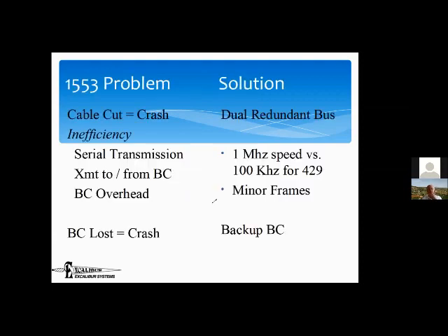Okay, so now let's talk about the pluses and minuses. We'll start with the minuses. And the first minus is that by virtue of the fact that we've reduced 16 wires down to 1, you've also got a single point of error for every single device on the bus, right? And if the devices on the bus are things like radar, engine, landing gear, you really don't want to lose communication with those things, right? Because the plane's going down. And therefore, 1553 always has redundancy in it.